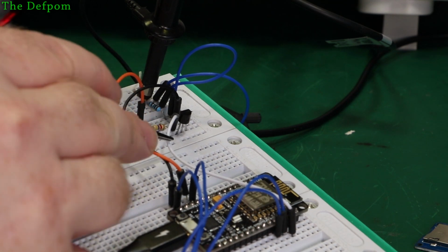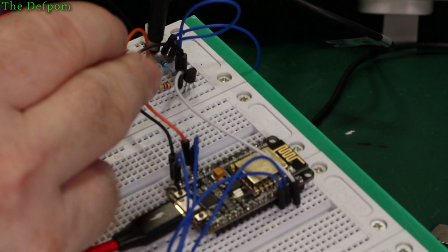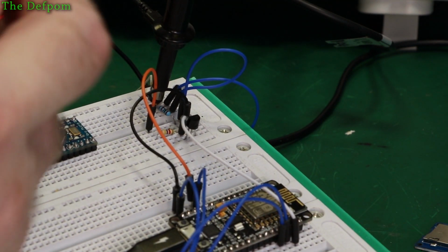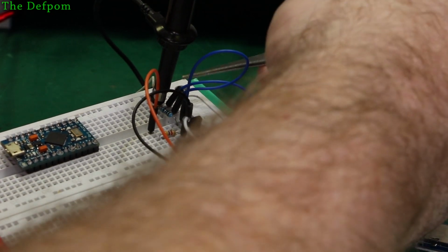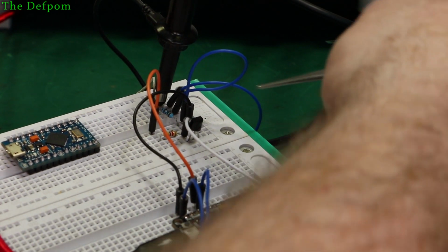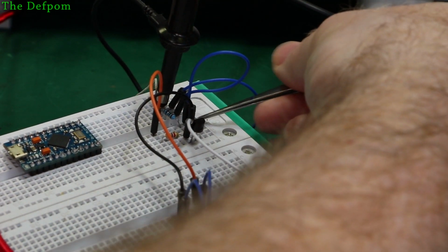It's a bit hard to see, I'm afraid. That's feeding the base, which is the middle pin. It's a 2N3904 transistor I'm using here. Just off the shelf, just a standard thing, nothing particularly complicated about that. And the ground side, because it's battery powered, it doesn't really matter, so the ground side's coming down, so it's common grounded all together. You need it anyway, probably. This wire here is going to my Scope Pro, ignore that. This wire link is just to bridge across here, so it's not actually used.